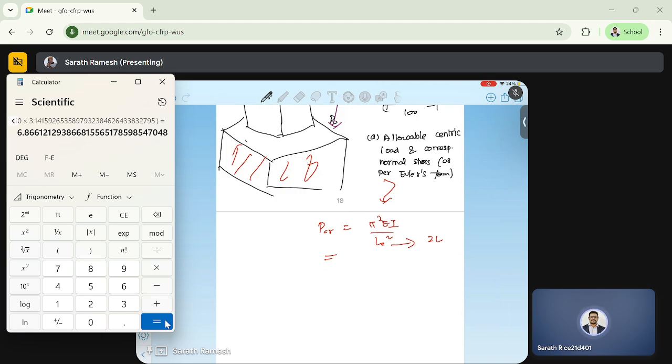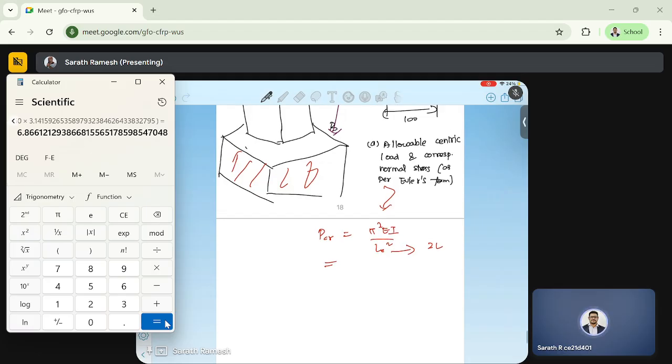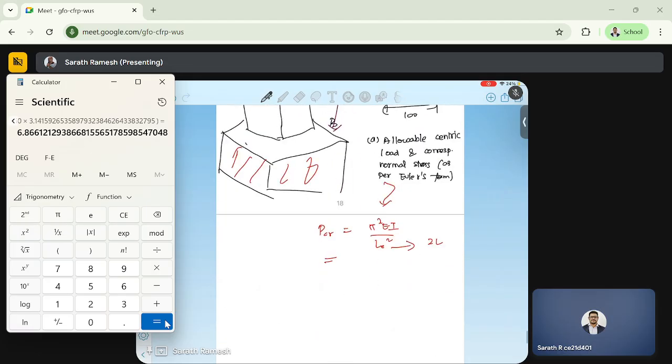The second part of the question, we are asked, assume that the allowable load found in the previous part is applied at an eccentric distance of 20 mm. So in subdivision B, they have given eccentricity as 20 mm from the geometric axis of the column. Determine the horizontal deflection of the top of the column and the maximum normal stress.